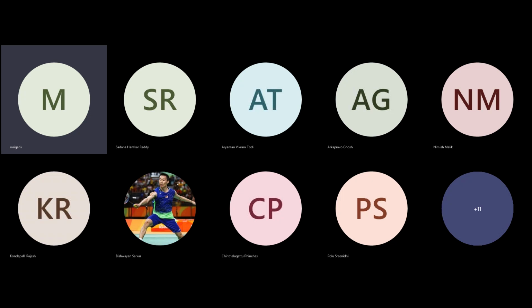There we need large devices. If you look at the driver device size that we have currently, it is almost 36 micro, and that into almost 30. So it is almost 900 micro. It is like a programmable strength. The MOSFET size is programmable, but the maximum size allowed in the design is almost 900 micrometer. That is in 65 nanometer technology.